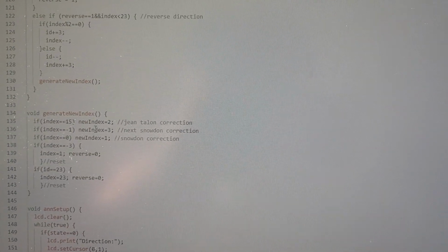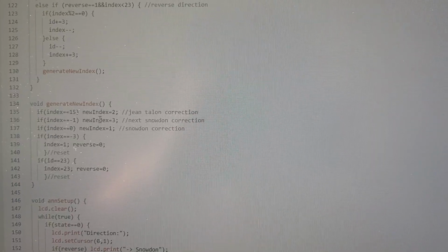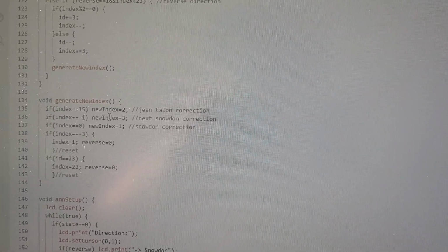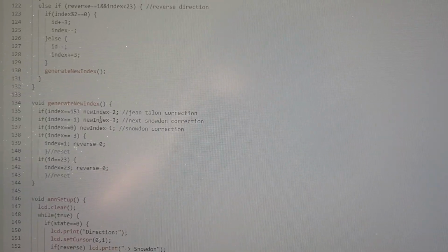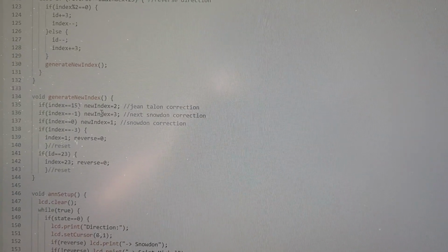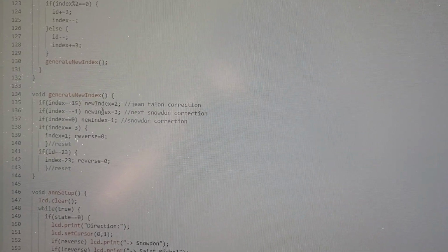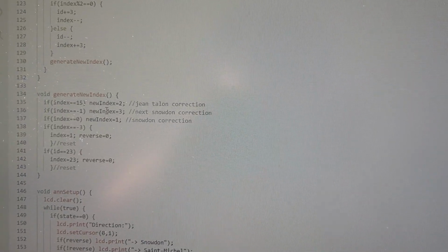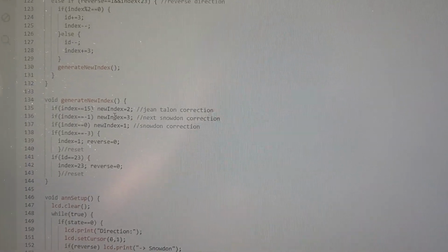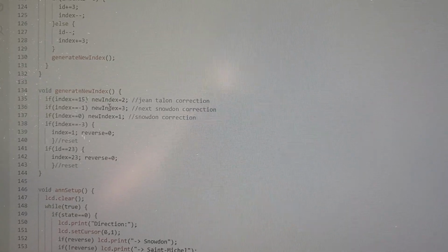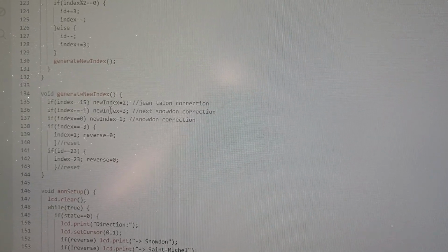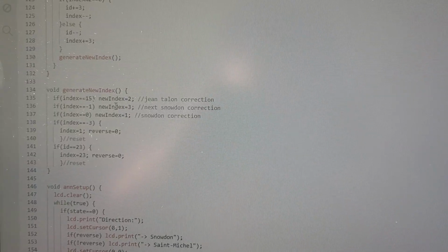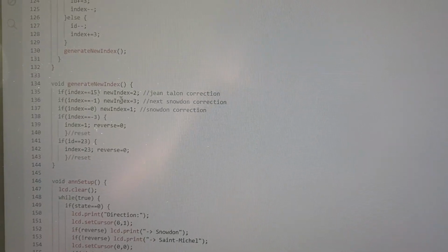This right here corrects any issues because apparently the SD card has a specific format for the files. So it doesn't use file names, it just uses numbers like 001, 002. That is the exact format. I don't know why it must be 3 digits, but that's the way it is. But for some reason, despite this numbering, there are occasional issues with the files when, for example, file number 025 might play before file number 023.